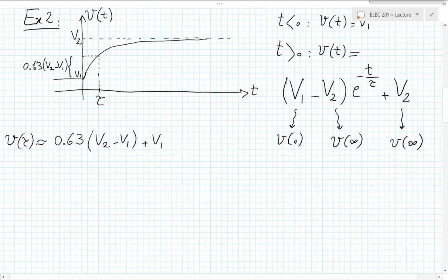This is something that very often people make a mistake about. They assume that if you hear about time constant, you should throw in 0.37. Well, 0.37 where is the question. Of course, if you have an equation like this, you can just put the time tau and get the answer. But the real insight is that the 0.37 in this case is here.